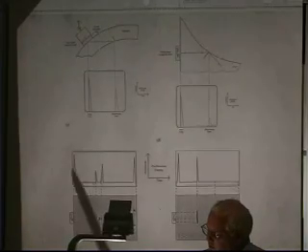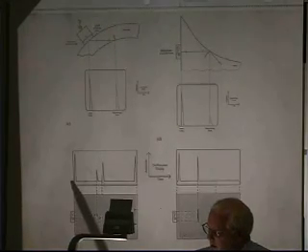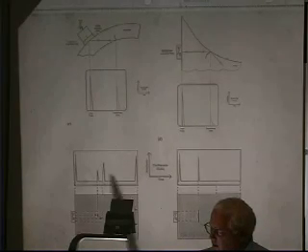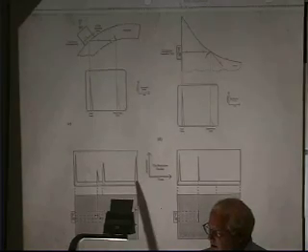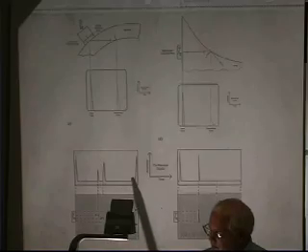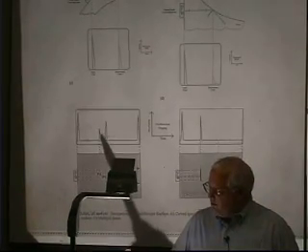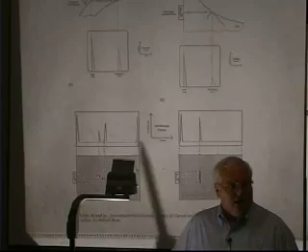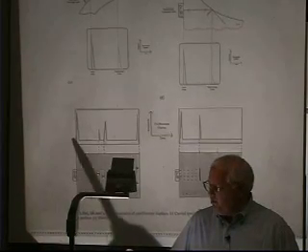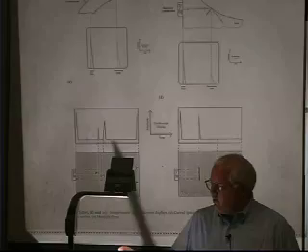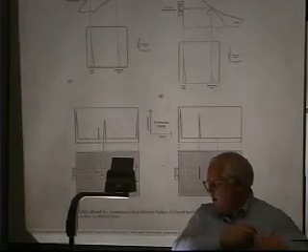But in this case, if there was nothing in the thing, it would go all the way to the back side and come back, and the time that takes, this is time on this axis, you'll get a peak over here. If there's a flaw in between, you'll see grass growing in the area in between. So here's your output signal, this is your reflection back for a good part, and this is something in between. Now, you can pick up things pretty well. It's gotten better and better.